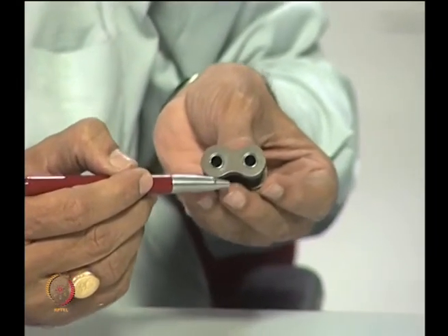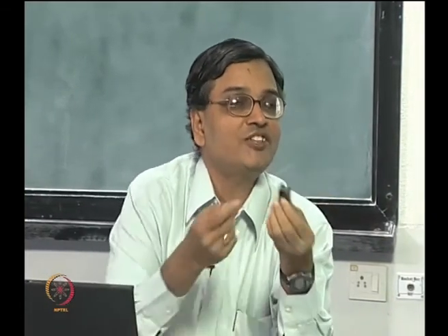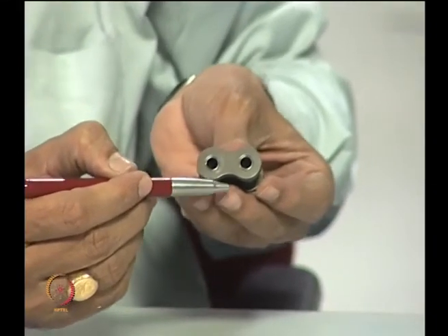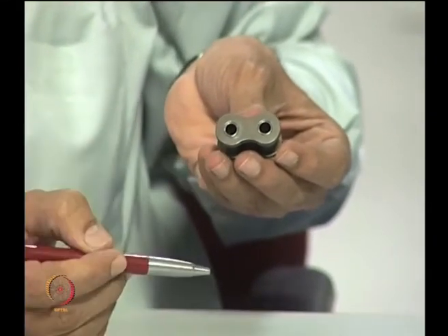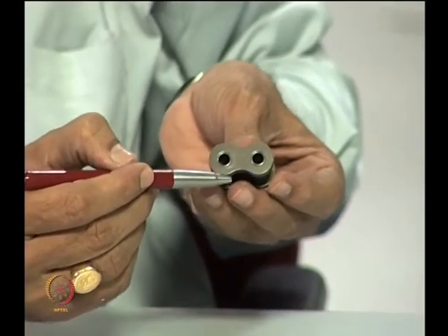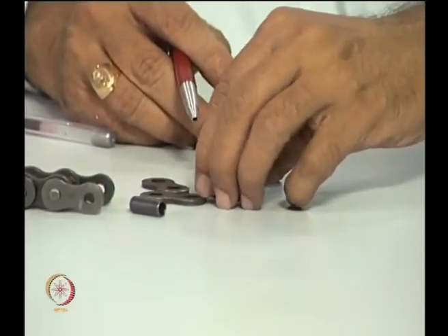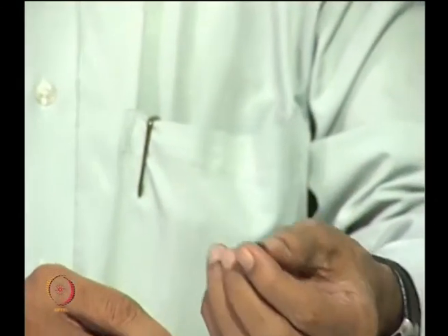So, this is done with an interference fit. So, apparently I do not have any external load on this chain link, but because of the way it is manufactured, you have stresses developed, you have a bush here, you have stresses developed very prominently here, and it is comparable to the service loads. The stresses developed are not small in value, they are comparable to the service load.